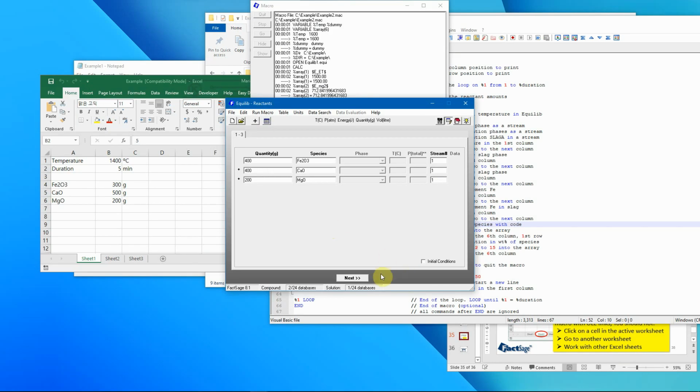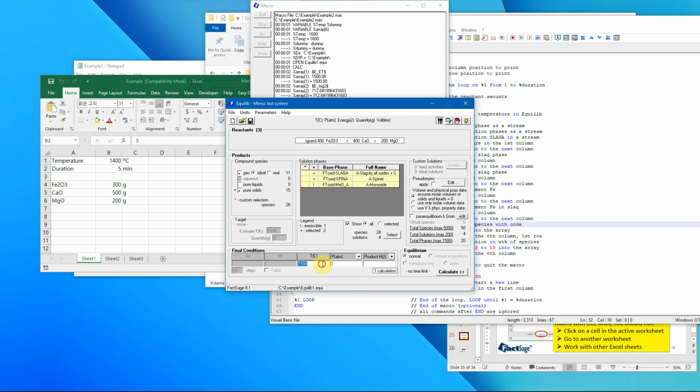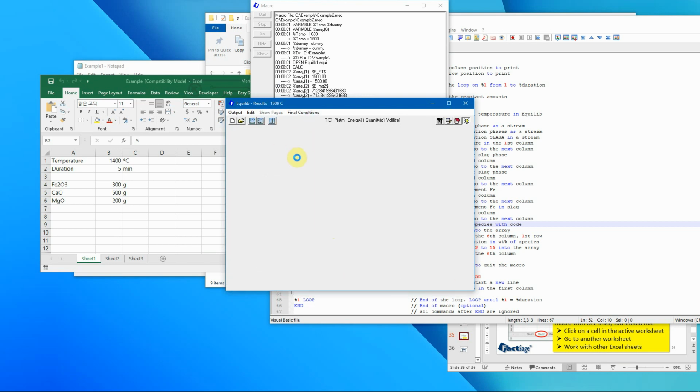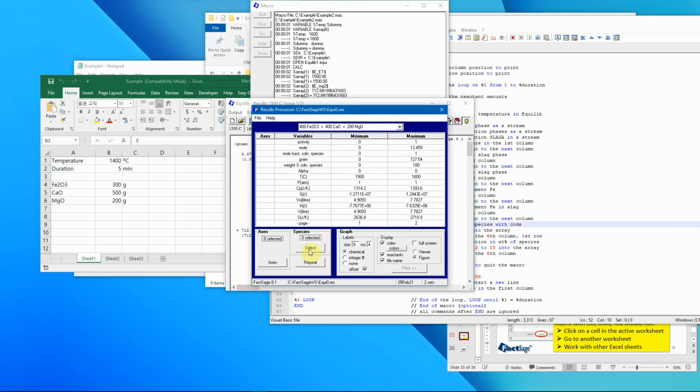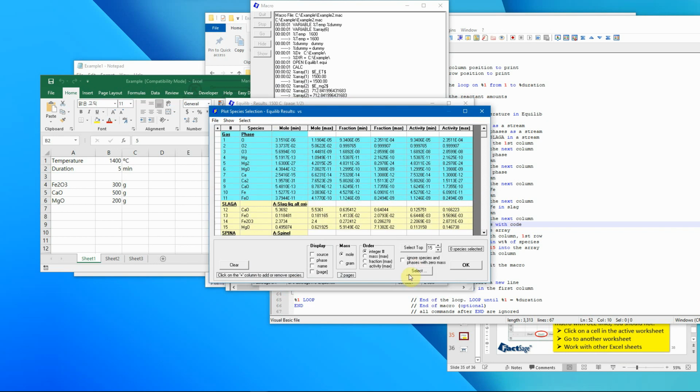So if I go there, and if you remember how to do this, do 2 temperatures and calculate to get the plot function working, and then go to the table. And I want to have the concentration of these, basically of these 4 species inside the slag. So I need to have these codes 2, 12, 13, 14, and 15.